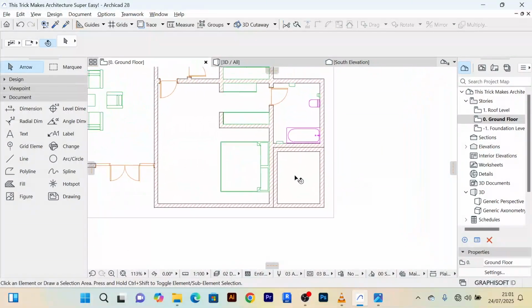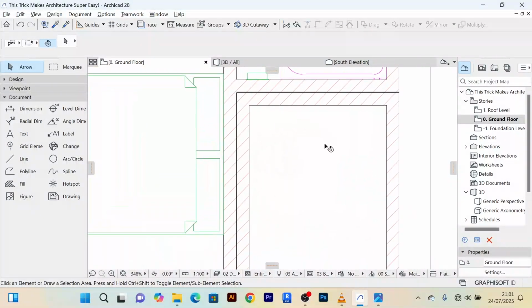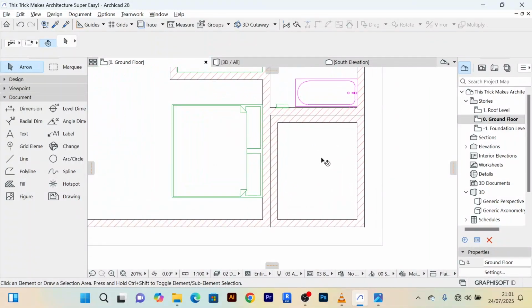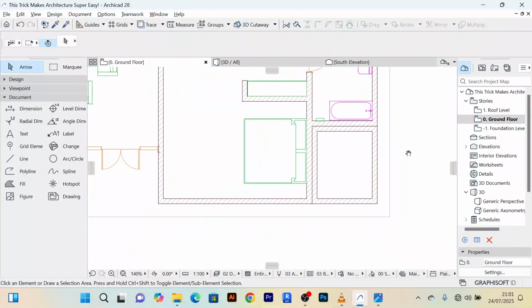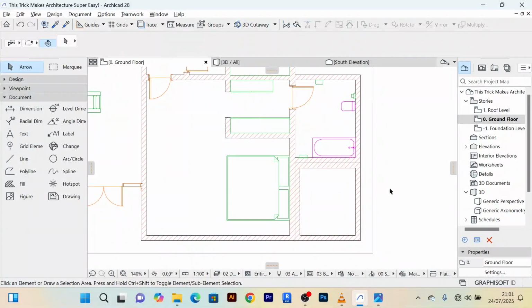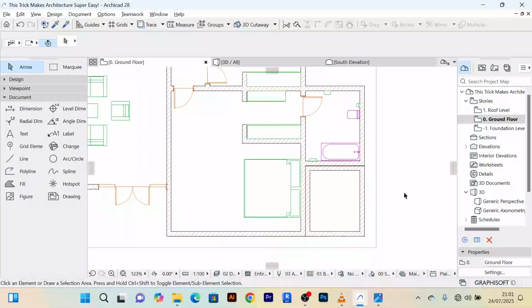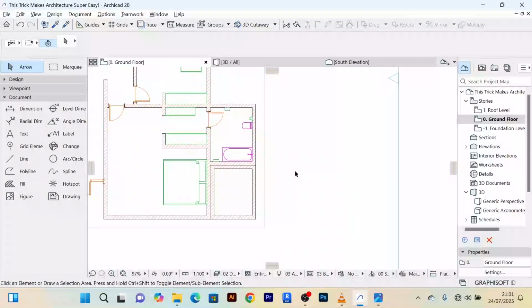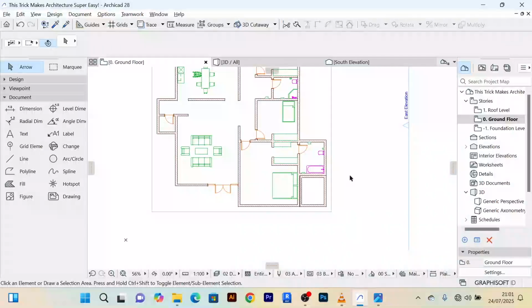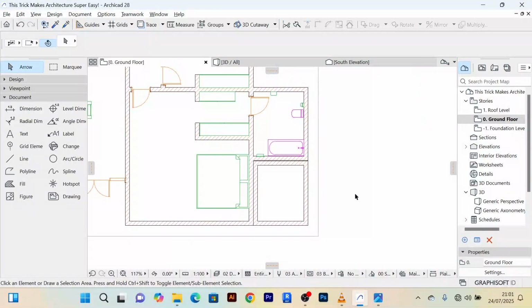So I remember telling you this is going to be a duct. It's not really a room. A duct is a space, an open space where all the pipes for the sewage are linked to, and from the duct it goes to the manhole. From the manhole it's supposed to go to the septic tank, then to the soak pit. So this is going to be our duct.